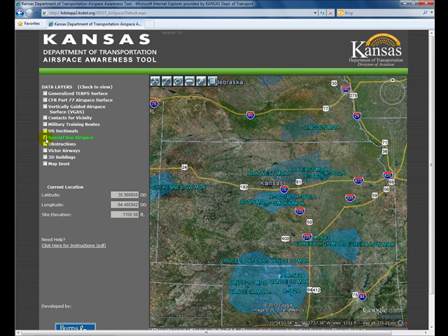Special use airspace is an area reserved for certain flight activities that must be confined because of their nature, or where limitations are imposed on aircraft operations that are not a part of those activities, or both. Typically, this airspace has a floor-ceiling boundary and operating hours for which these restrictions apply. The restricted areas are controlled by the FAA, and aircraft are prohibited from operating in these areas during certain hours and altitudes.